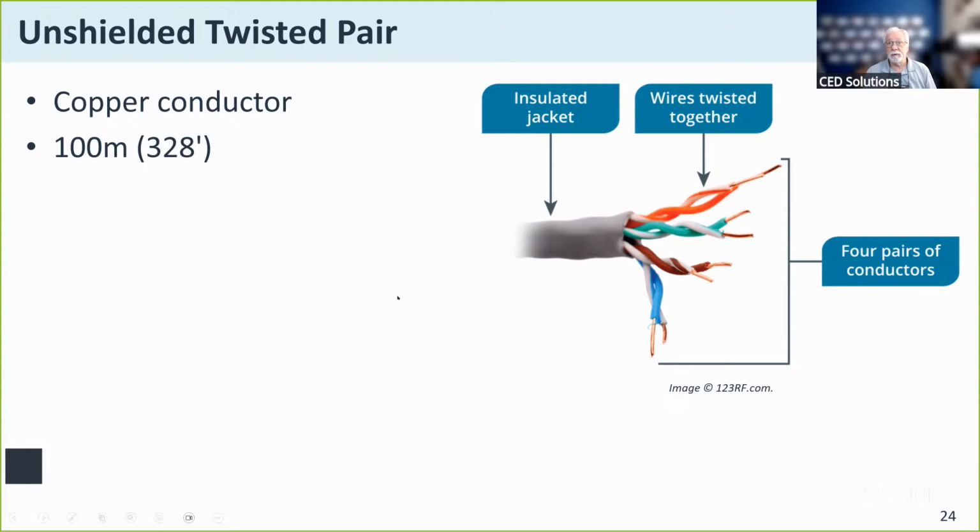The cabling is typically broken down in what they call categories: category 5, 6, 7, and now 8. This is a version called UTP, unshielded twisted pair. There is no additional grounding or shielding that is wrapped around the twisted pairs inside the cabling. It uses this old gray, and some of them the blue, PVC wrapping. A lot of this, they don't allow you to use anymore in new construction because this old PVC casing, when it burns, lets off noxious gases that kill us human critters.